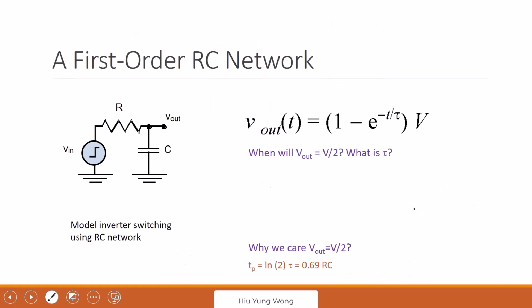Now I want to just go back to RC delay, right? Probably you all know, just now someone asked why it takes infinity. Just because of this equation. If you have a pulse, you take t equal to infinity in order to get to the Vin, the VDD.